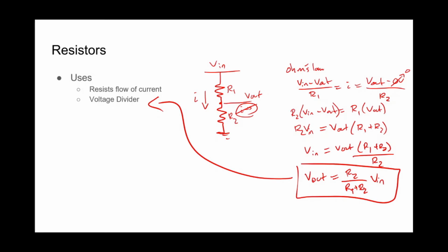Okay, now we talked about voltage dividers. This is great. If you wanted to measure the battery voltage of something, that's wonderful. Please don't use this for power regulation, to drop the voltage for a motor or microcontroller. And let's talk about why really, really fast.